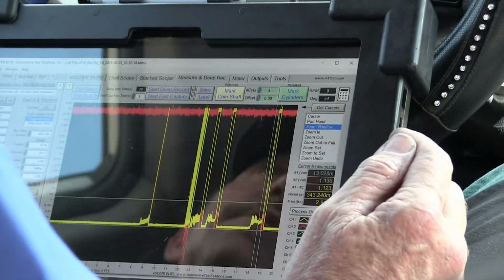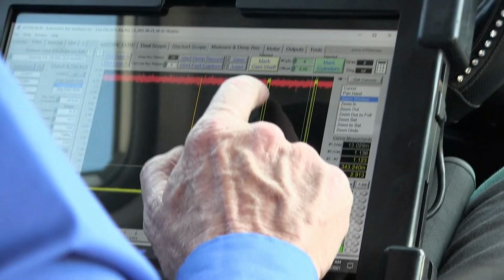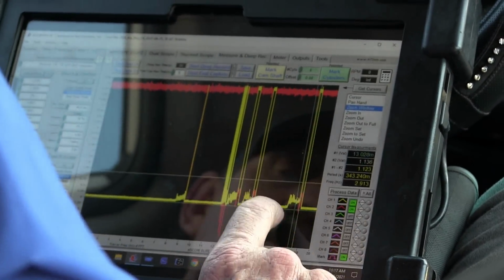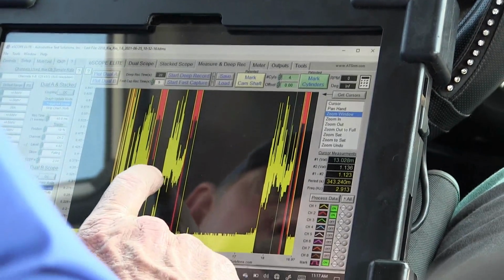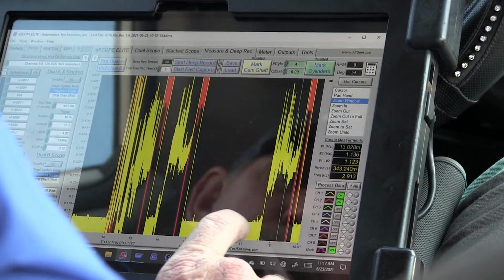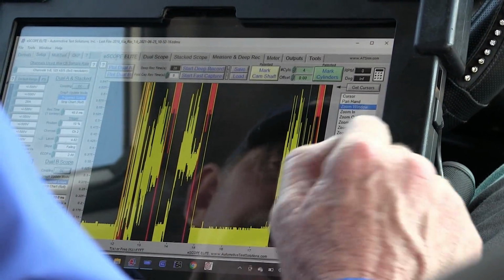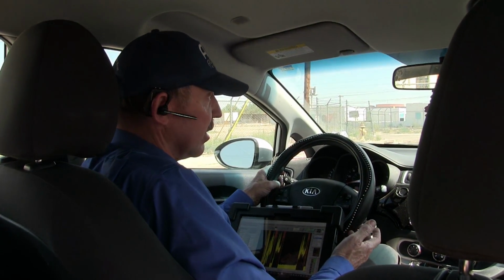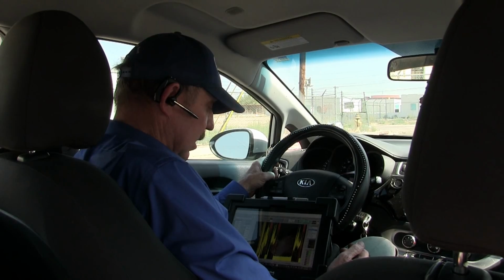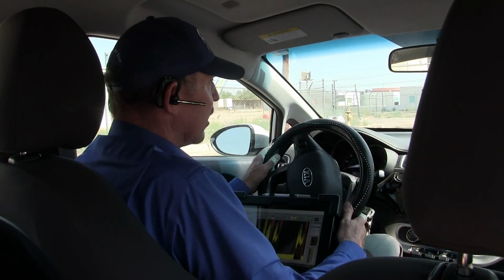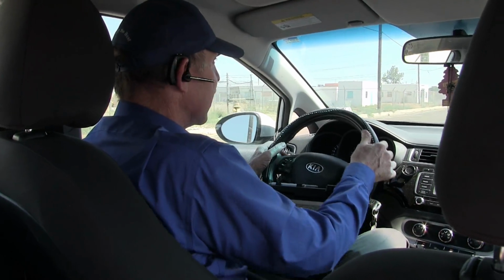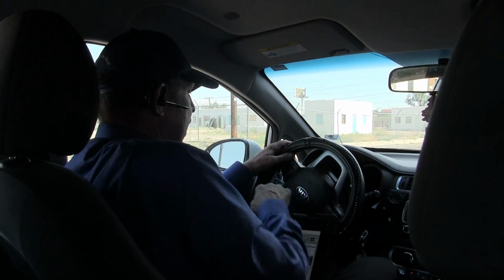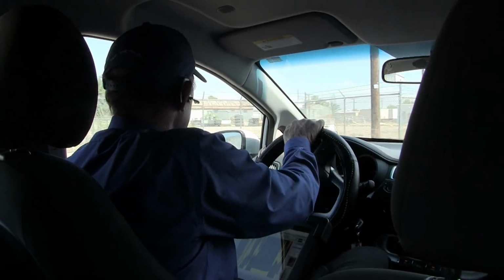Okay, so let's look at this. So we'll take our zoom window. We can see that we came up to 5 volts. Now the only way that circuit can have 5 volts is if I lost my ground. But down here, once again, I have something and then I come down and I'm at a ground plane. Okay guys, so right now I think the problem is the sensor, the connector, or it's the sensor. So let's go back and let's wiggle the wires and that sensor and see what we can figure out with the scope on it. If I've got the scope on it, I should be able to see what fails.